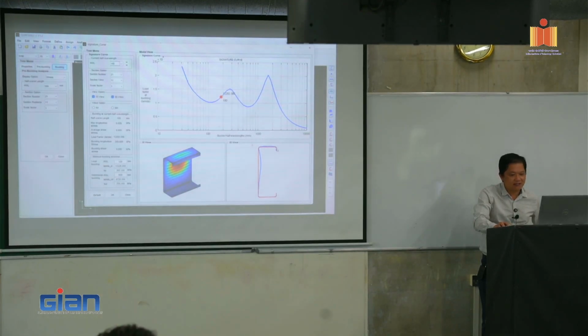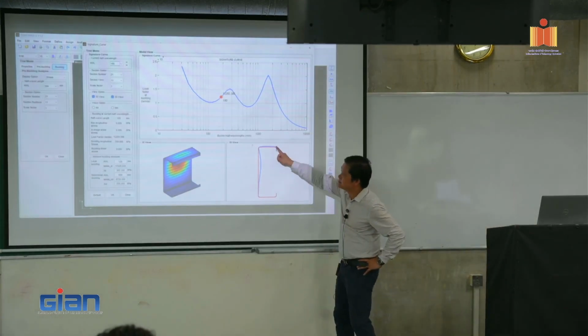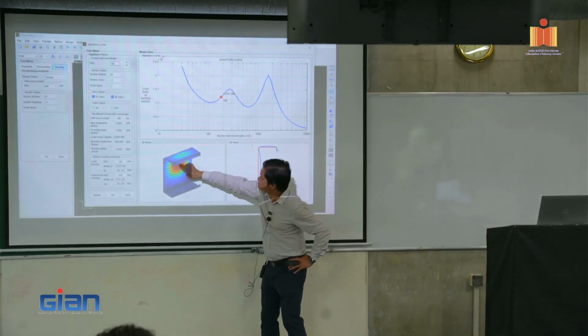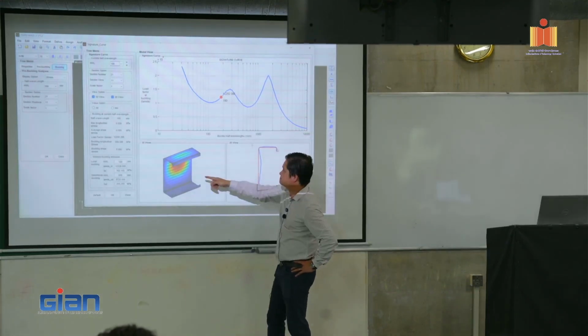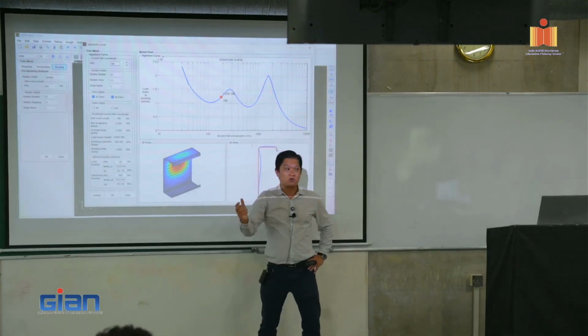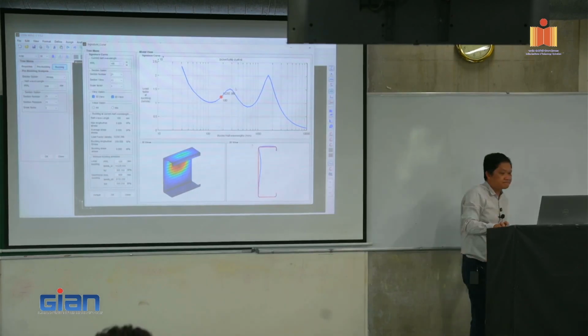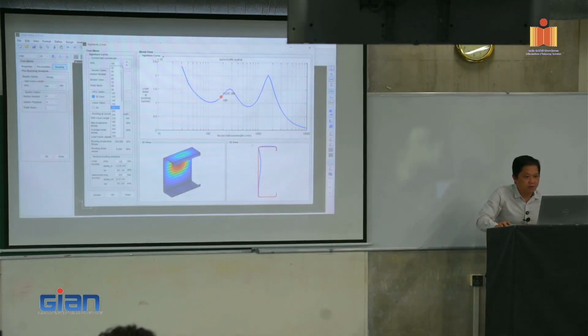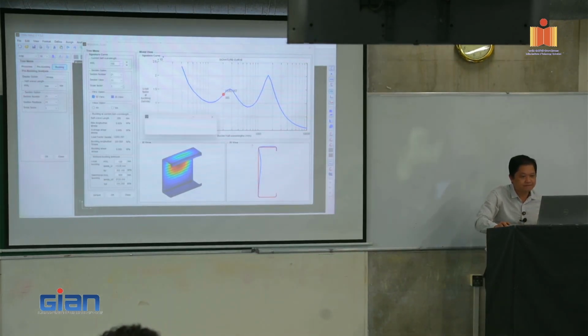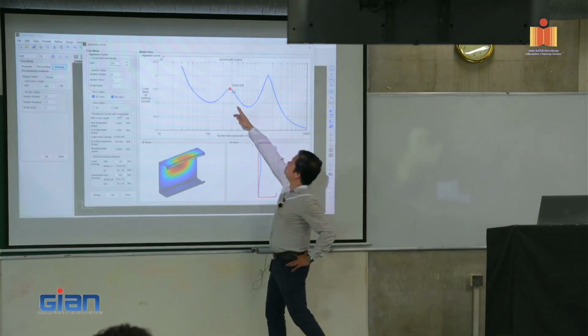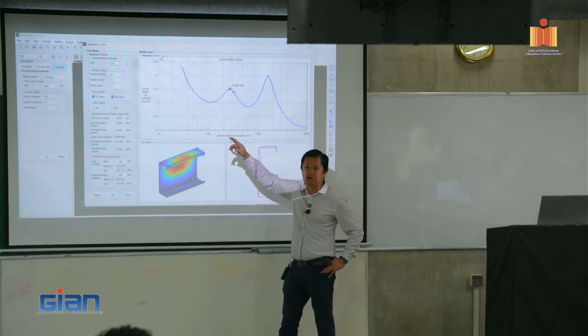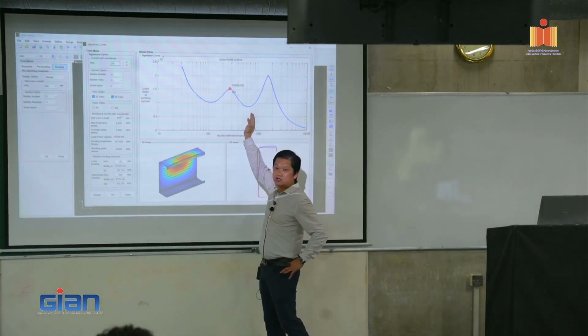So this junction, pay attention to that junction line. Still straight. It just buckles here, up and down, in and out. Just very local buckling. And go up to 200, local buckling, 270. Then you can see now it's going down. So from here to here, the mode changes, right? Change from local buckling to distortional buckling.